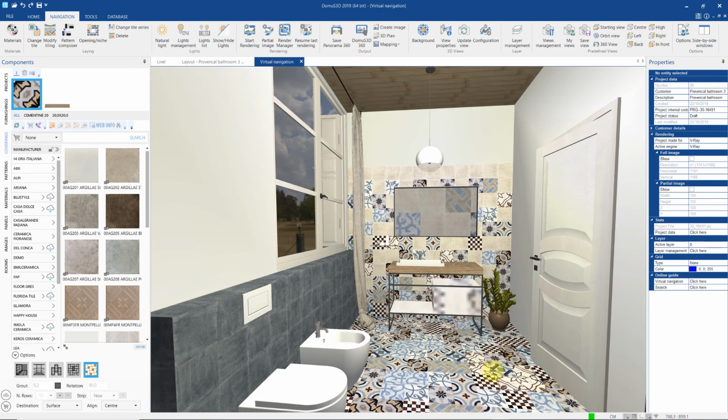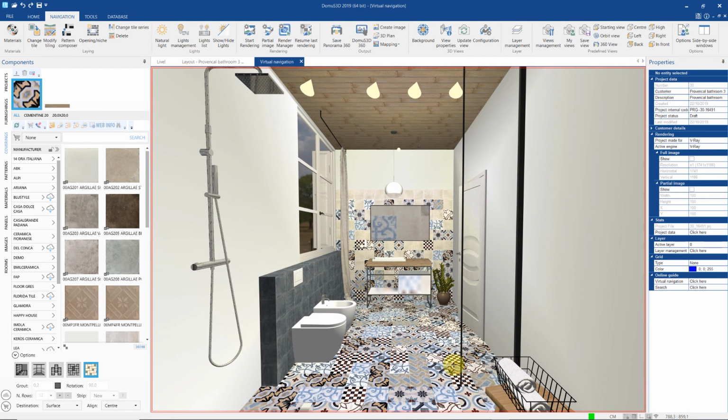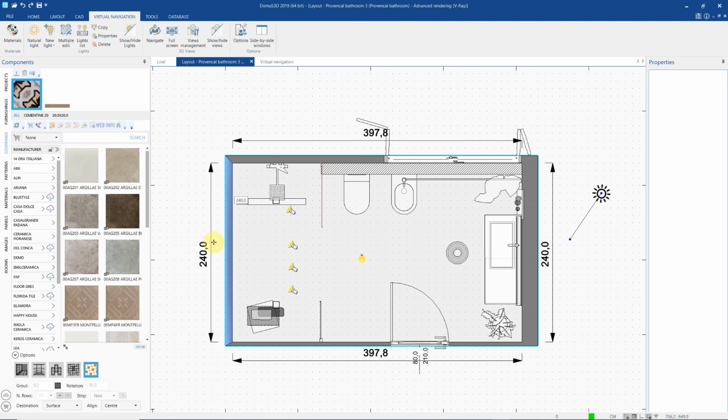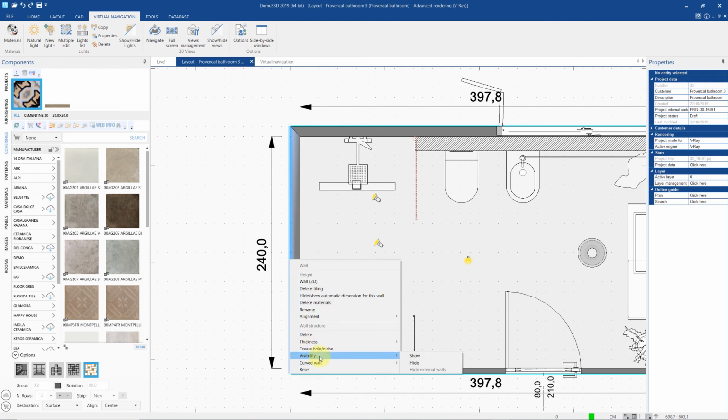Now, let's look for the right viewpoint, or the portion of our room scene that we want to render. Like we saw previously, the red border indicates that our current viewpoint is outside of the room. In fact, our hypothetical camera will be somewhere around here. This could represent a problem because we have the exterior wall which will block our view into the room. In this case, however, all we need to do is hide the exterior wall by selecting Visibility and then Hide.